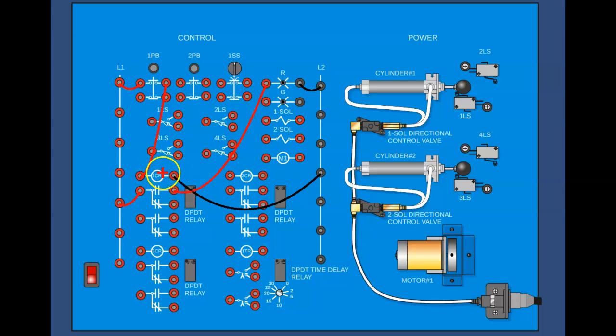And this relay coil is not going to be energized until we press that push button. So let's turn on our power, and notice our lamp is not on. We're going to manipulate this switch, and notice that as soon as we do, we energize our relay coil. The energizing of that relay coil changes the state of this contact, causing our lamp to be on.